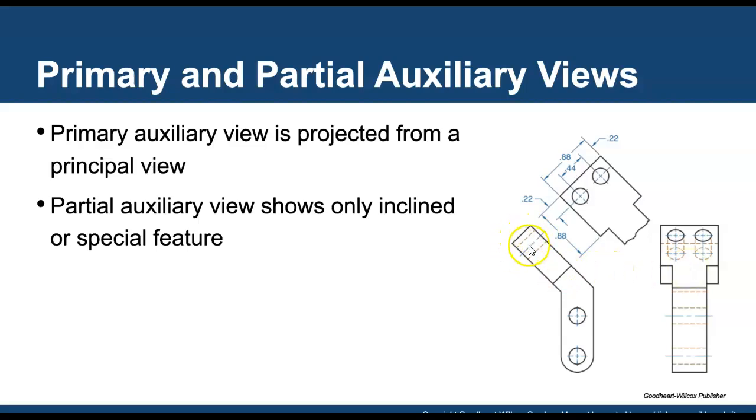In order to tell what the true size and true shape is, we project into an auxiliary view. Imagine our hinge line going right through here, parallel to that particular edge, and then we can more or less move that on the hinge to see. Now you can see from this example that the auxiliary view shows us the true size and true shape, and it also gives us a good way to put some tolerances on and know exactly what these dimensions should be and where the placement of those holes should be on that part.